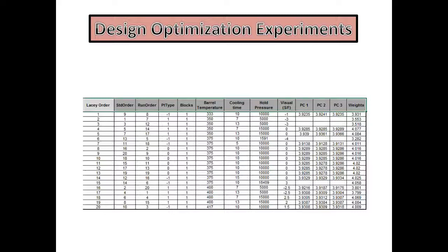Now, it's important to note that anytime that you make a barrel temperature change, such as the 333 to 350, you're going to basically shut the press down. You're going to make your change to your 350 straight profile. Then once the temperatures come up and stabilize at 350, you're going to restart the press and run it for 15 to 20 minutes so that you can get a heat soak condition to see what your parts are going to look like.